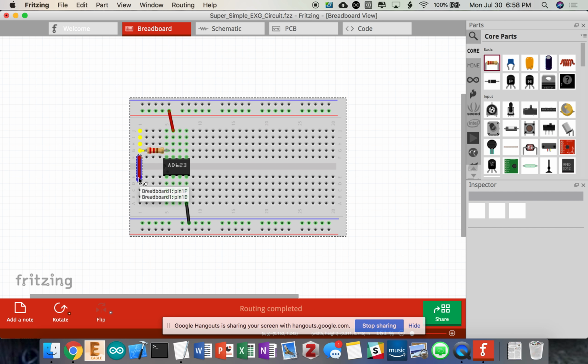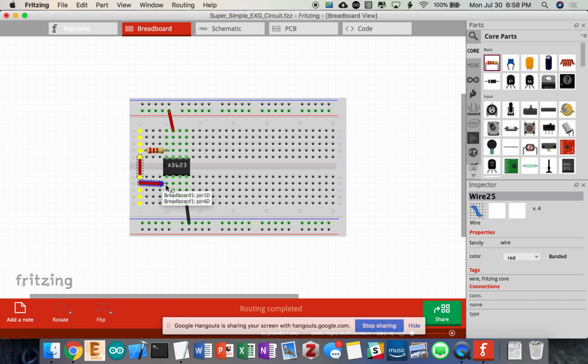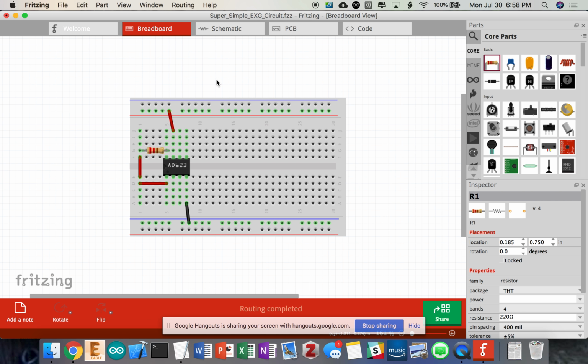So if you put an electrode on your arm, then you won't read the nerve signals, or you will? If I put it directly on, that goes into what's called surface EMG. If I put the electrodes on the surface of my skin, as opposed to cutting open my arm and touching the nerve individually, I'm getting the sum of the electrical signals. That will let you know when the nerves receive an impulse to your muscles to tell them to contract or relax, and you can actually take that information and do stuff with it.